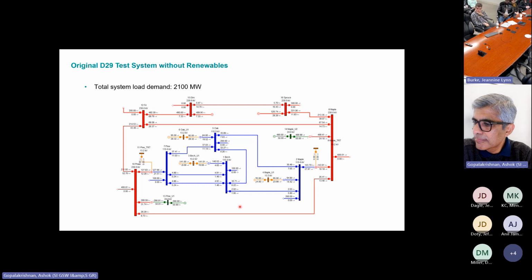Sure. So regarding the CTI coordination problem, I've also seen situations where a protection panel has the primary side and the secondary side, where the primary side has all the line protection relay, traveling wave relay, the bus protection relay, and the secondary side has exactly the same thing. So the primary side is doing the same job the secondary side is supposed to do, and they are in the same location in the same panel. So I'm trying to relate this to what you said about CTI, where there might be some kind of miscoordination if the two relays are in the same location doing the same job.